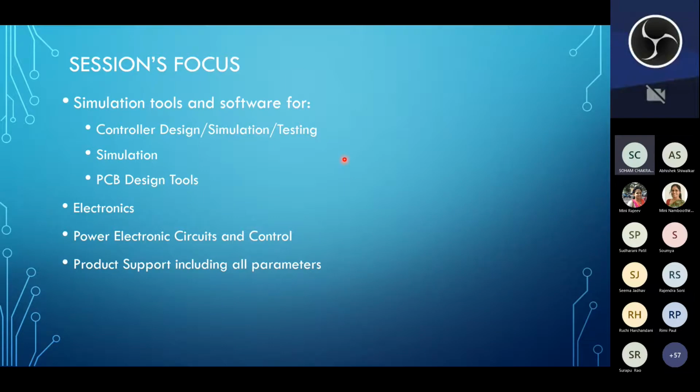So when we go for PCB design, as you remember in the previous sessions, we saw that in power electronic circuits, components interfere with each other. There are some cases which need to be taken care of while designing, the controller part and this power circuit part, and you need to take care when you mount them or operate them together. Until you simulate or design a controller part separately, it will work absolutely fine. When you design your power circuit separately, it will work absolutely fine, right?